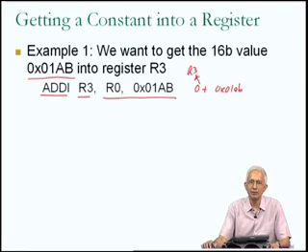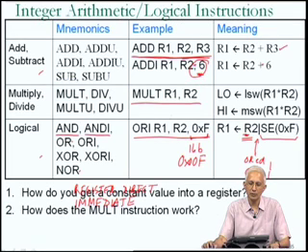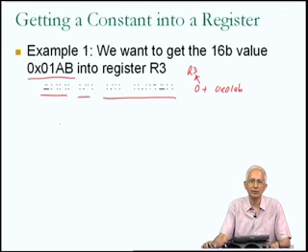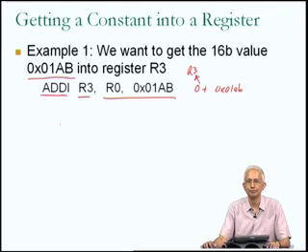So, when you read MIPS1 programs, you will frequently find the add immediate instruction being used for a purpose like this. If you look back at the table, you notice that I could just as easily have used the AND immediate or the OR immediate, several other instructions which could have been used in slightly different ways. But this is possibly the easiest way of doing it.